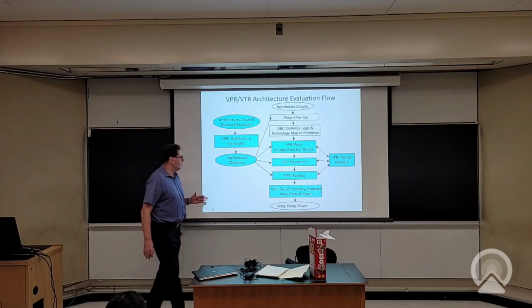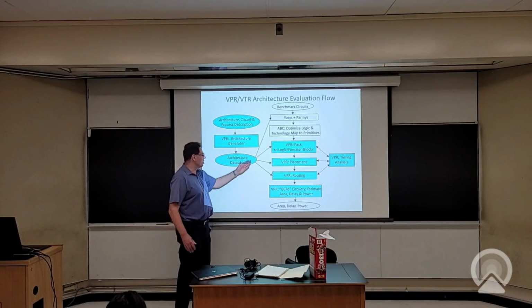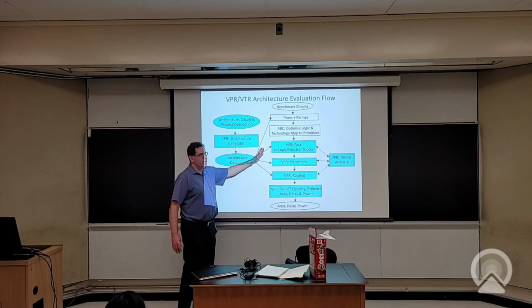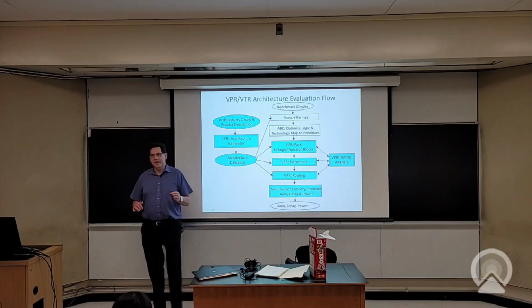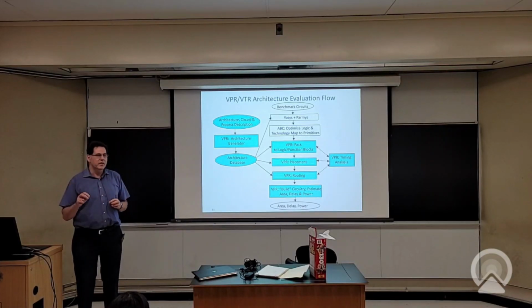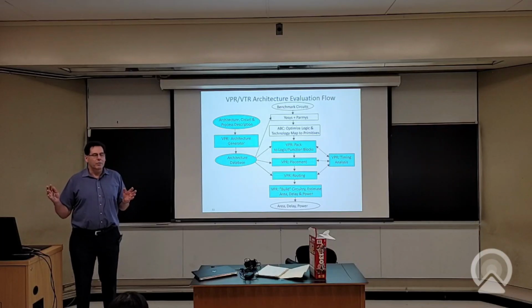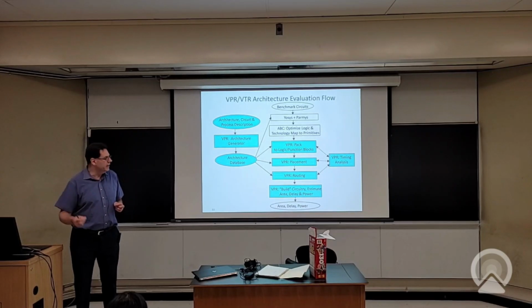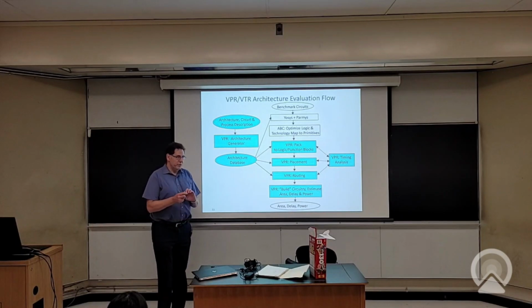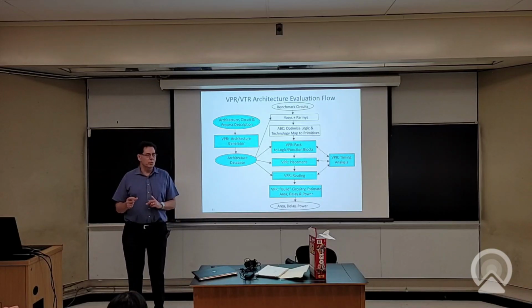And you're never sure, right? So a lot of FPGA manufacturers use their production tools. They'll make small architecture changes, so Quartus or Vivado, for example, would be production tools. You make small changes in the production tools and try to evaluate it. You have high confidence for small changes because you go, we've been beating on this tool for like 10 years.